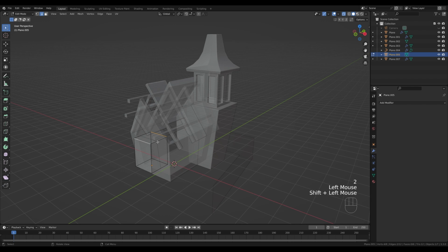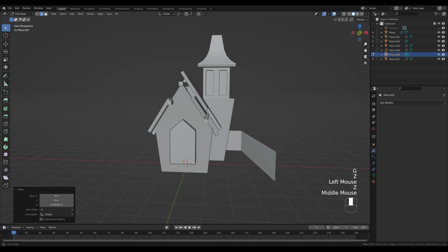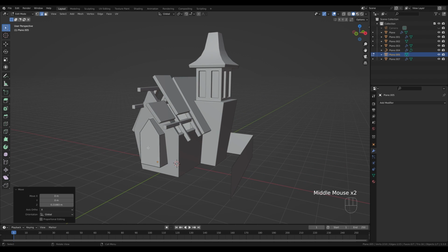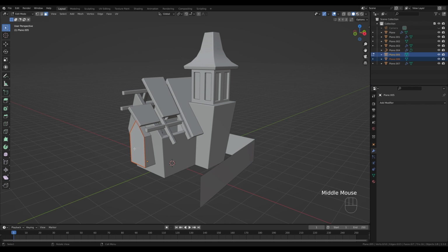Select these two edges by holding Shift, right click and choose subdivide, so we can select this edge right there and bring it up so we have some nice, you know, vintage style window. And now go for face select, select the front face and press Shift D, right click to release, and P, enter to separate into a new object. We'll make use of that later.